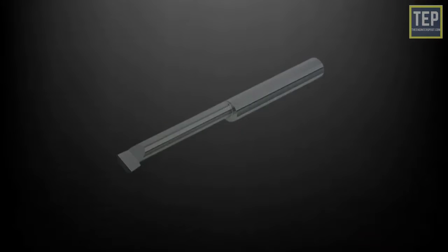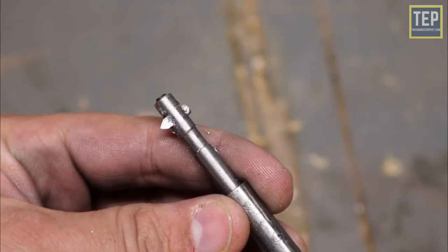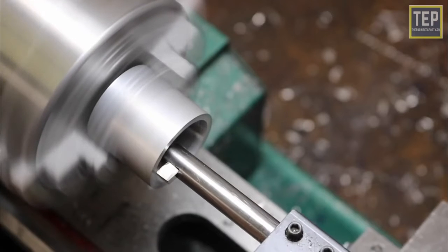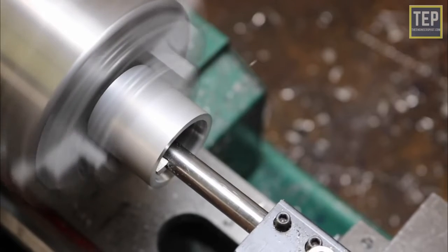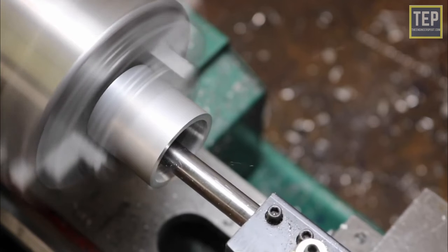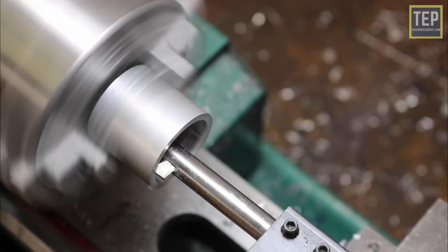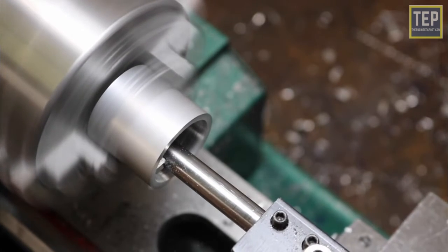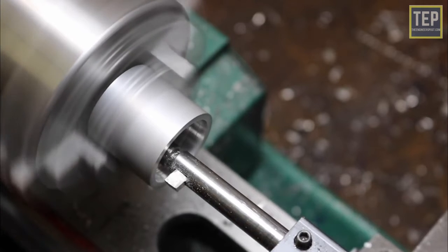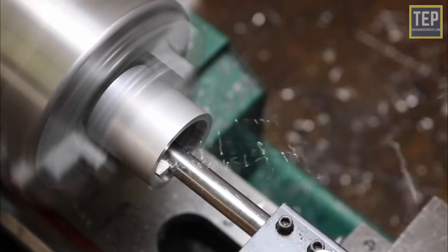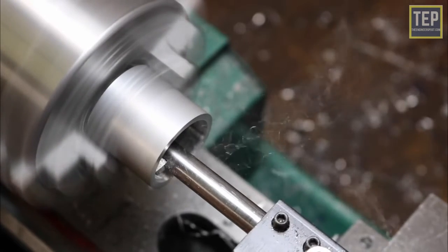Boring tool. A boring tool is similar to a left-hand external turning tool, so far as its cutting edge is concerned. The tool may be a bit type inserted in a boring bar or holder, or a forged type having a tool shank. A boring bar is made of mild steel with slots, or holes, cut into it to accommodate the tool bit, which is locked by an Allen screw. The amount of projection of the cutting edge of the tool from the center of the bar determines the finished hole diameter of the work. The bit is generally inserted at right angles to the center line of the bar for boring a continuous hole, passing from one end to the other end.